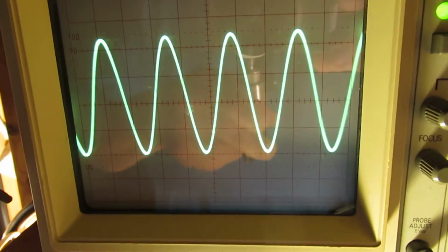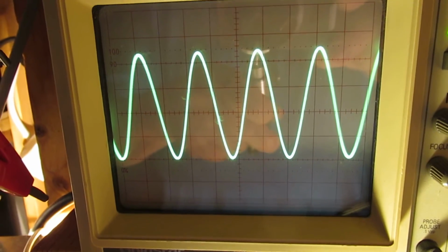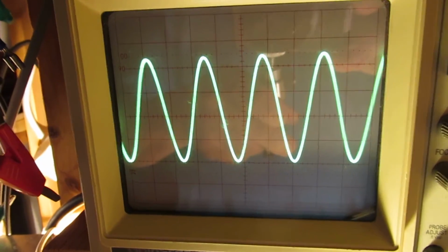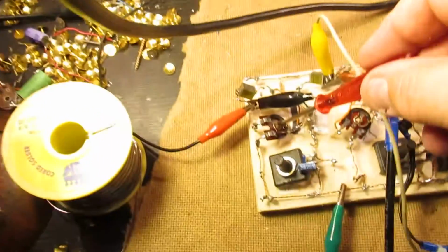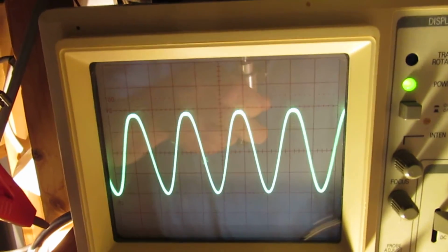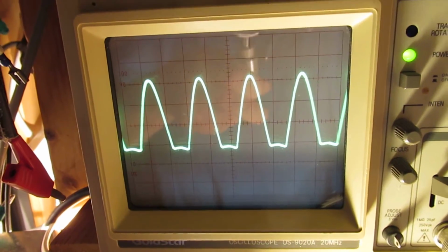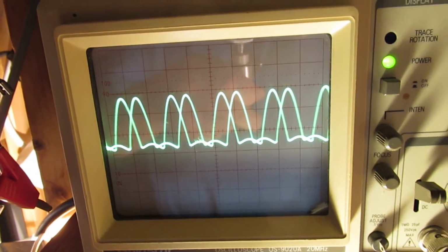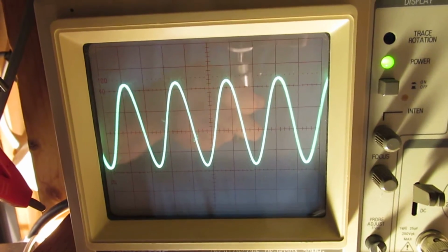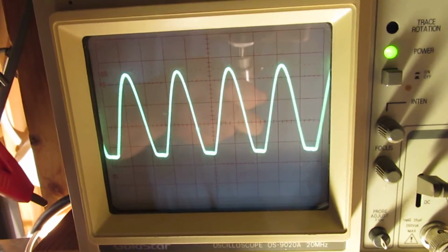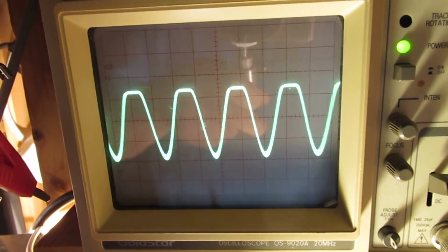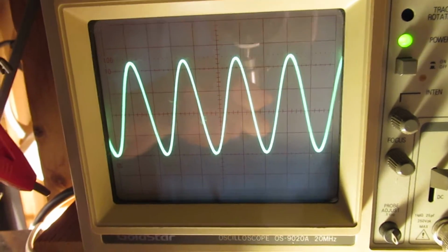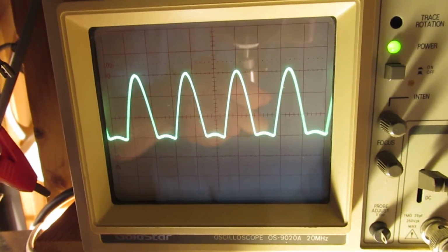This is the waveform at the output of that one transistor amplifier, and I'm now changing here the biasing, and you can immediately see that small changes in that potentiometer value have an extreme effect in terms of audio distortion. So that's the reason why I advise to use a potentiometer in audio circuits.